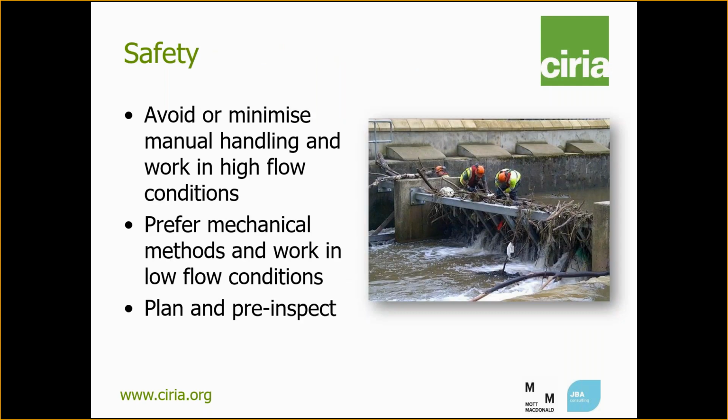Approaches to safety have advanced as a result of new law and operational experience, and we have much greater awareness of the hazards associated with manual handling of debris and working on screens in high flow conditions. So we have a new safety chapter which emphasises carrying out risk assessment to compare the culvert or the screen with the open channel alternative, and a move towards retaining open channels wherever possible, constructing culverts and screens only when there's no viable alternative, and removing or daylighting redundant structures where possible.